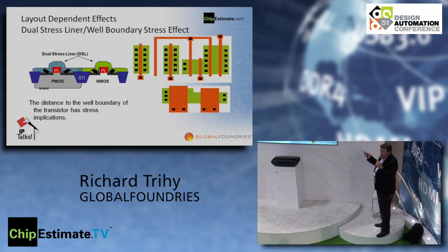Another issue that I highlighted at 28 nanometer, where we initially saw it, is layout-dependent effects. So layout-dependent effects are caused by a couple of things, but I'll highlight first the dual stress liner, which is a technology that adds a compressive force on the PMOS and a tensile force on the NMOS. And this has the effect of increasing the performance of the transistor. So stress is good, okay? So it's a good thing.